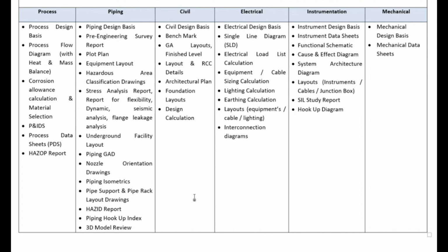Sometimes, that 160 meter benchmark we have put there, they will consider in the civil drawing as a 0 level. So for this plot, that is a 0 level. Now the compressor will be plus 2 meters. The civil building will be plus 3 meters from that 0 level benchmark. The pipe rack will be plus 7 meters like this, correct?